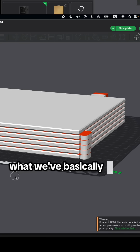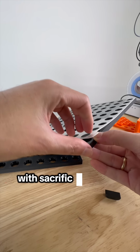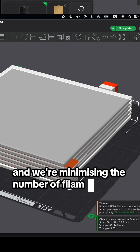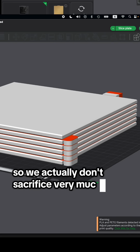So now what we've basically done is we've created our own custom PETG interface layer with sacrificial support blocks for the tab, and we're minimizing the number of filament changes that need to happen for this print, so we actually don't sacrifice very much print time at all.